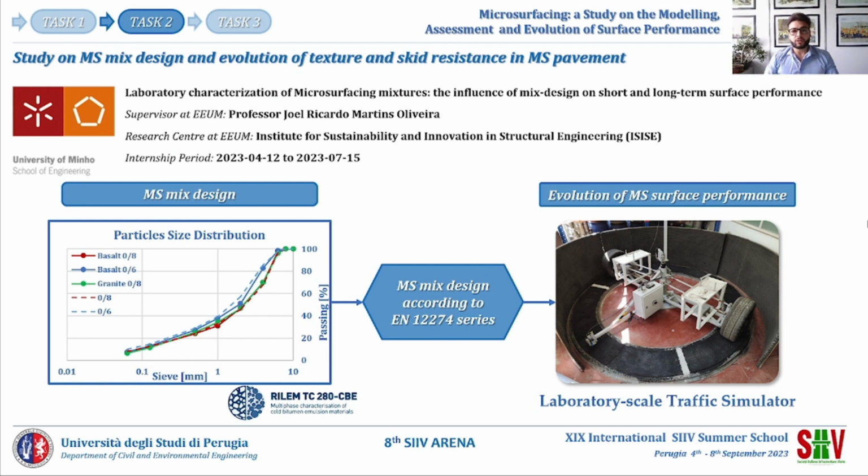Here we focused on manufacturing 3 different microsurfacing mixtures: a basalt 08, a basalt 06 and a granite 08. The gradations are provided by the RILEM Technical Committee, which deals with cold bitumen emulsion materials. Then, by means of a laboratory-scale traffic simulator, we focused on the evolution of the microsurfacing surface performance.